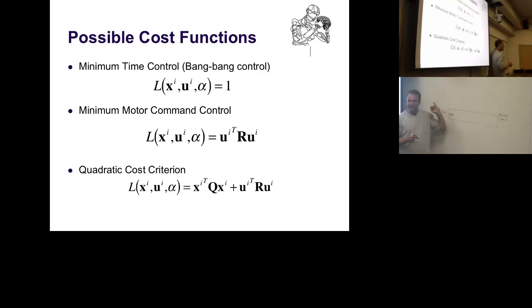So one bang is take maximum motor commands you can generate. And then when the right time comes, and that is now the magic of the race car driver, you hit the brakes like a crazy person, just the right way, so that you brake with maximum deceleration, stop on the line. So this is actually interesting. So the control policy for that is actually incredibly trivial. It's binary. It's just full blast or full blast off. That's why it's called bang-bang.